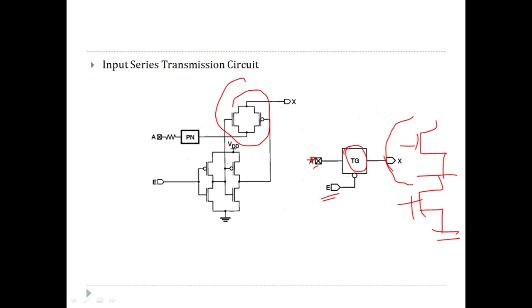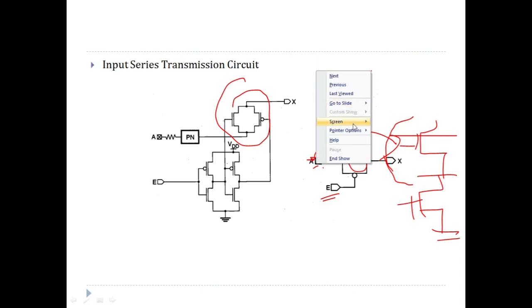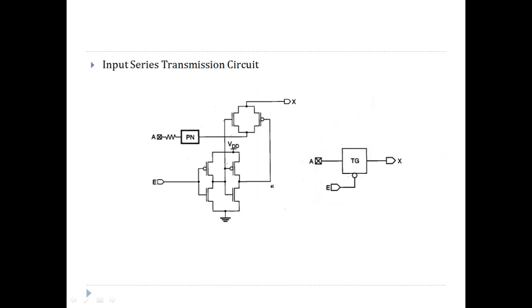Now, there is a signal called the enable signal which acts as a strobe, which allows the signal to pass from the input pin to the digital logic, or it blocks the signal from passing from the input pin to the internal logic. So basically it will act as a tri-state.